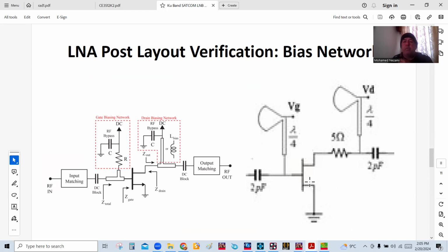This resistor for that specific device, when I designed it and when everybody else designed this, they usually end up having to stabilize this LNA device so that it's unconditionally stable over all the frequencies. They add this resistor in here, okay? You can go to Gonzalez's book and see the explanation of why you would need to do that. That's a very common practice. Sometimes some people put it on the input, but in my case, we put it on the output because this is an LNA, and as you know, the noise figure gets impacted by anything that produces thermal noise at the input side. So we put it at the output side.